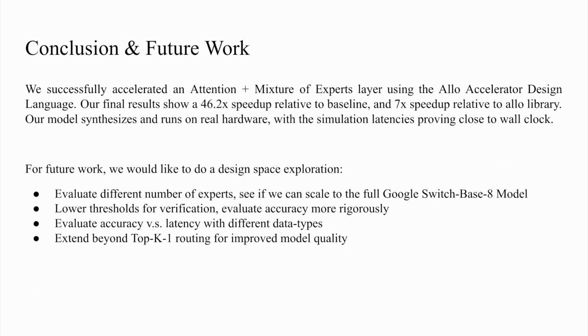In conclusion, we successfully accelerated the attention plus mixture of experts layer using the Allo accelerator design language. Our final results show a 46.2x speedup relative to baseline and 7 times speedup relative to Allo library. Our model synthesizes and runs on real hardware with the simulation latencies proving close to wall clock.